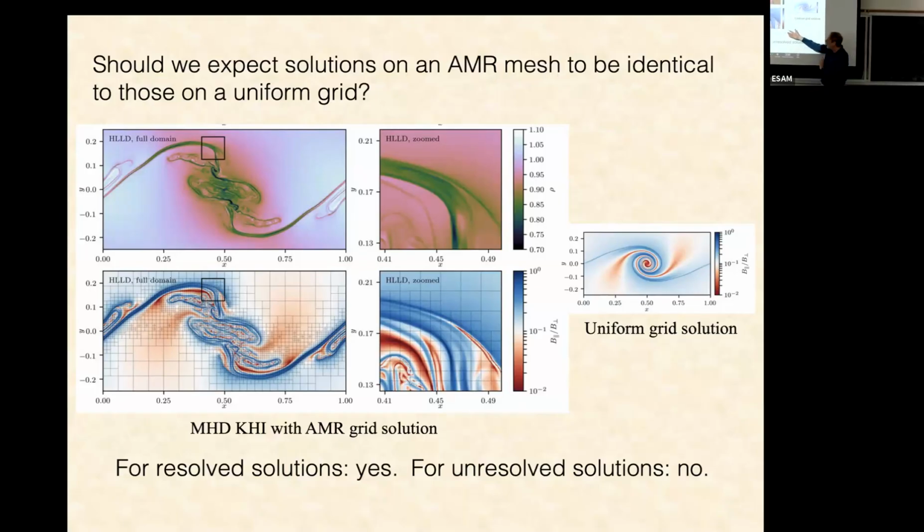The one good thing about finite volume methods is that you know the truncation error satisfies particular constraints. It's always diffusive. So it's a little more controlled than just random noise. But on the other hand, it's still unrepresentable. I don't know exactly what it is. So I think a careful study would require putting in physical perturbations. I really only showed this to make the point that AMR is a very powerful but dangerous tool. You have to be very careful with it to make sure the things you're trying to measure are not being affected by unavoidable non-uniform truncation error that results from having an AMR mesh.